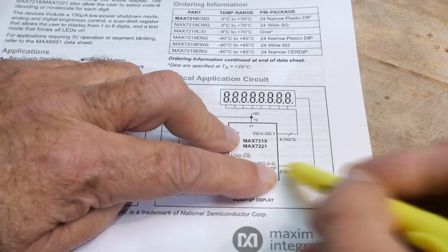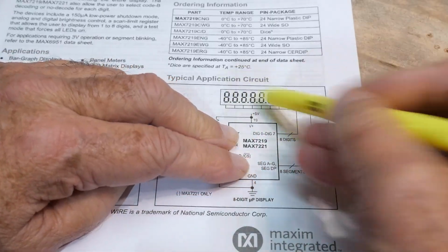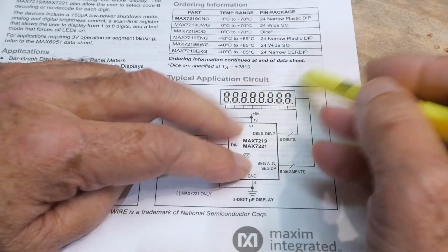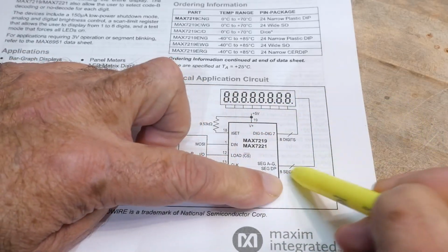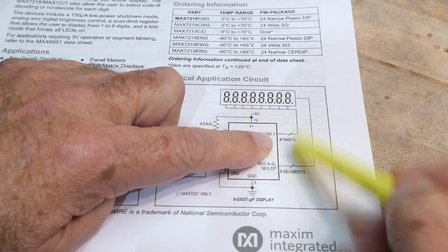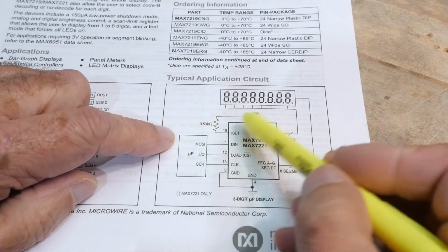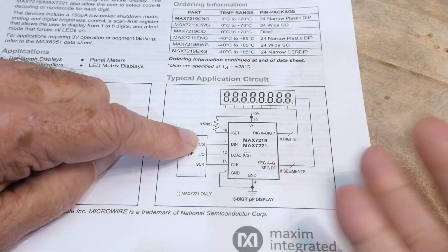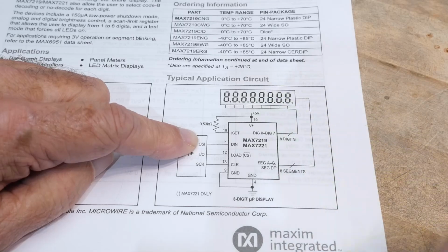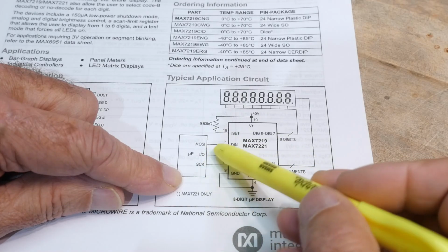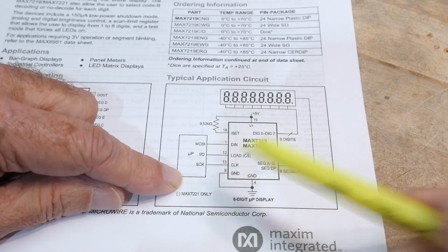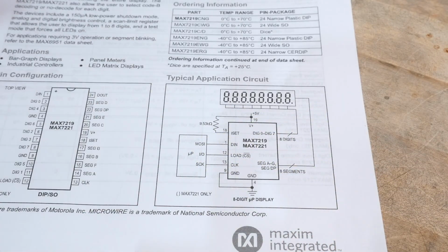So it's got 8 segments that drive it, it's a 7-segment display plus 1 decimal point, which is 8 segments. And then there are 8 digits, so it's 8 by 8. And you can set it so it has a particular drive current, so it drives the LEDs with a constant current, set by this resistor. And then you can just talk to it with clock, data and select. So there you go, these are pretty cool parts.